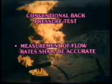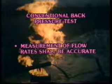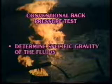The flow rate is measured with an orifice meter or critical flow prover. Orifice meter and plates should be calibrated and verified. Barometric pressure should be recorded. Specific gravity of the produced fluids should be determined. Pressures and volumes of produced fluids should be recorded periodically during each flow period. Stabilization occurs when both the flowing wellhead pressure and the rate of flow are constant for at least 15 minutes.